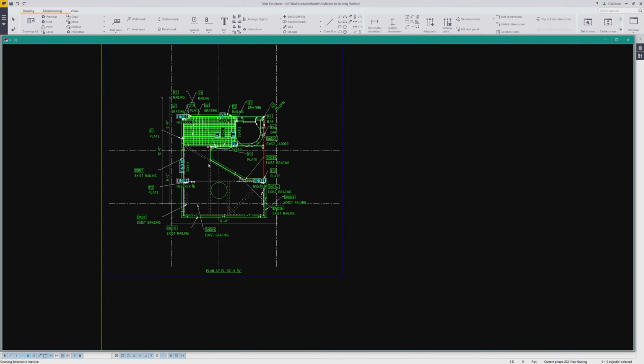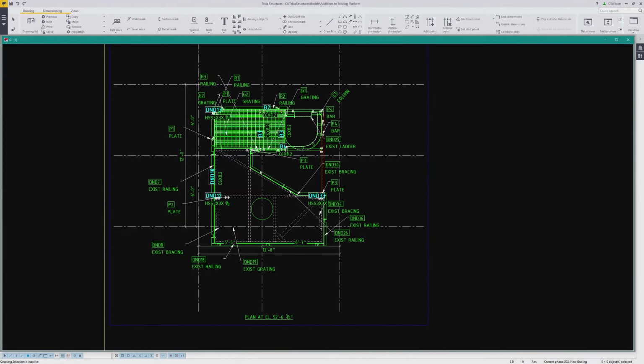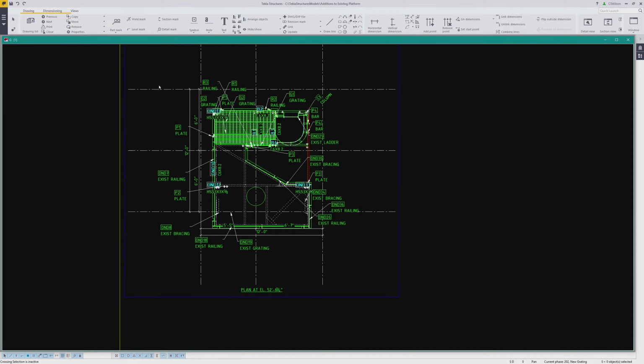With Tekla, you can be as automatic or manual as you want to be, which is, in my opinion, a huge advantage. So there really isn't any right way or wrong way to handle the drawings as long as the end product turns out the way that works for you. So with that said, I want this plan to end up as a framing plan, and I'll start by cleaning it up a bit. First, I'll delete off all of the marks and dimensions that were automatically created just by windowing in and deleting.